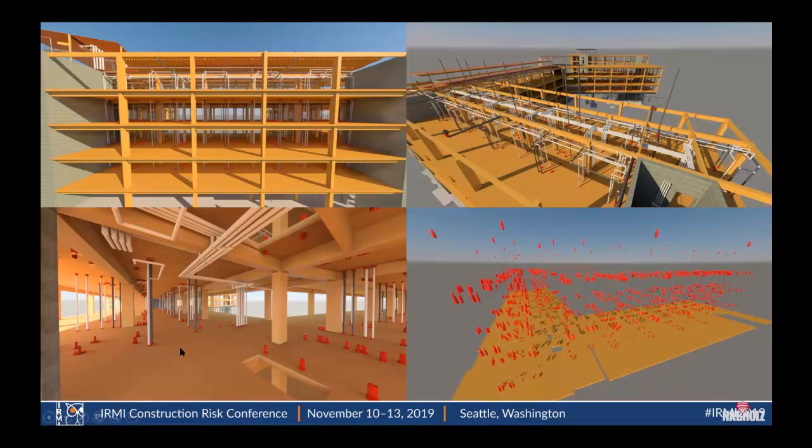Some things that we had to do, and you can kind of see it in this model, is the holes had to be oversized. At the time that we started this, Hilti had not come out with anything in the United States for fire-rated penetrations through cross-laminated timber. So we helped them do this research and write the book on UL assemblies through cross-laminated timber. So we had to oversize the holes, say 1.5 inches on each side or so, depending on what that assembly looked like.